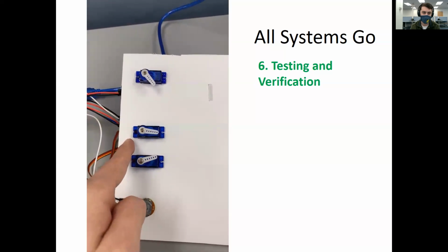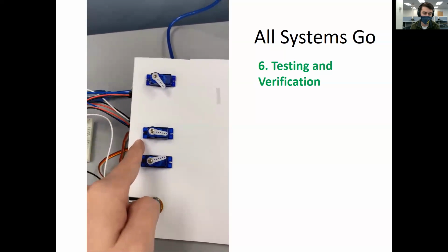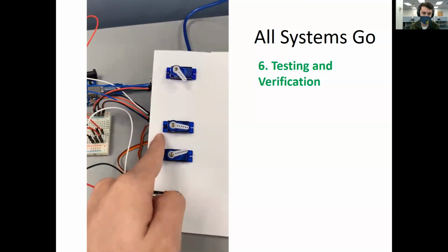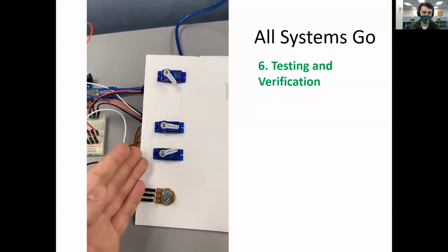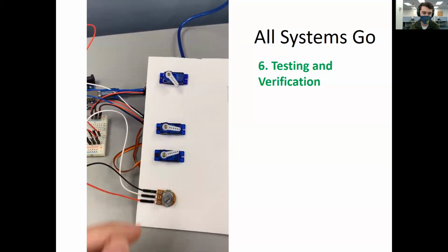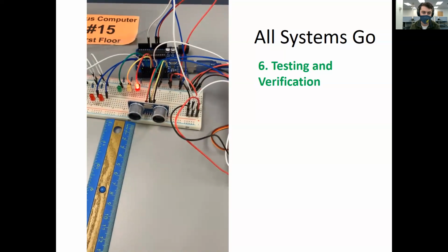I actually plugged the top servo into the ports that control the flaps, and it ran that program pretty smoothly. So that tells me it's not an issue with the code or the Arduino, it's just an issue with those 2 motors.